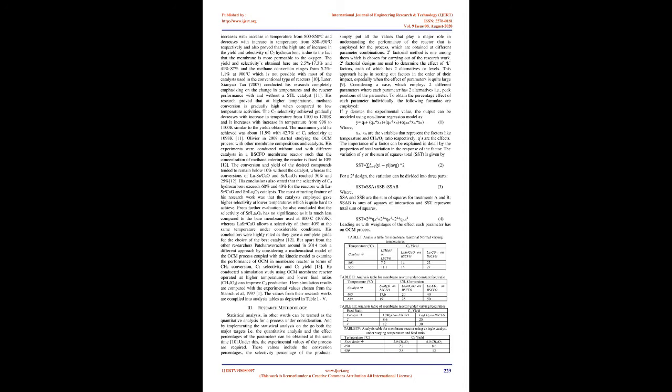At a certain fixed temperature and pressure, the porous membrane reactor is capable of achieving about 30% yield with 53% selectivity of C2 products, whereas fixed bed reactors and others provide a maximum yield of 20.7% at 52.5% selectivity [7]. Several parameters such as temperature, catalyst, and the ratio of methane to oxygen have a large scope of effect on the yield and selectivity of C2 products.